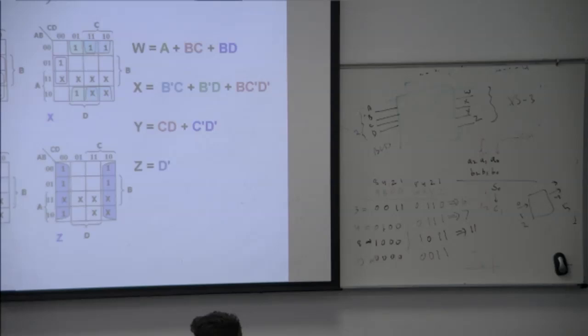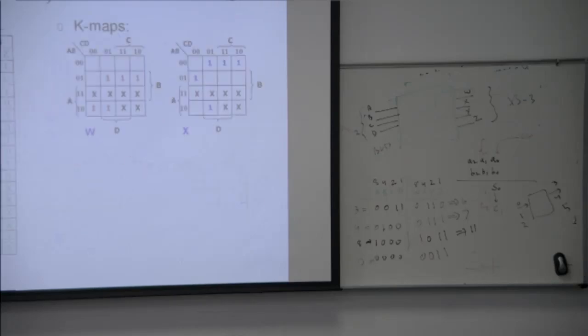This is just like a question. Alternately, I may also ask you another question. What is that question? Convert XS3 to BCD. So now WXYZ will become the input, ABCD will become the output, and now you have different functions. Yes, the don't care will change. Can you see here the don't care will change? Why will the don't care change?